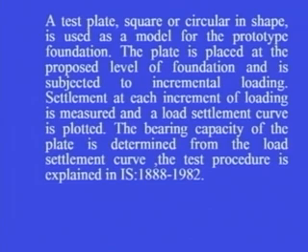The plate is placed at the proposed level of foundation and is subjected to incremental loading. Settlement at each increment of loading is measured and a load settlement curve is plotted. The bearing capacity of the plate is determined from the plate load settlement curve, and the test procedure is explained in IS 1888 1982.